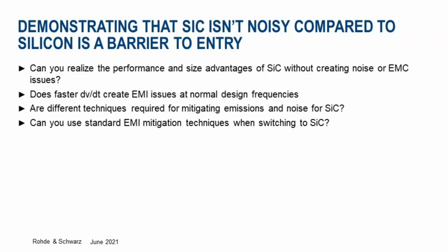Moving a design from silicon to silicon carbide offers the potential for higher performance and efficiency while reducing cost and size. The initial hurdles for silicon carbide were reliability concerns and price sensitivity. While these issues have had significant resolution, SiC may still not be a drop-in replacement. Implementation includes a learning curve for optimizing the design and addressing packaging issues. Now, noise is raised to the surface as a potential limitation.